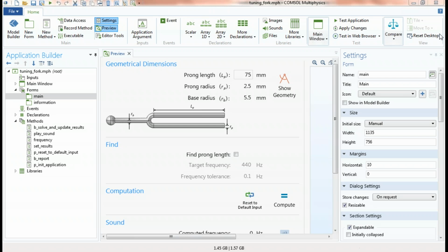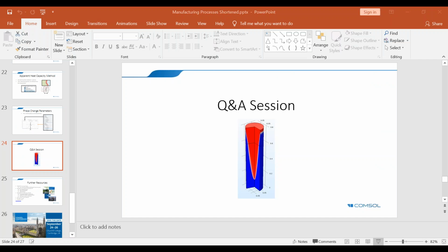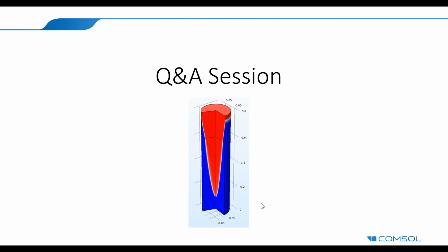So I think if you wanted to simulate this process, you would need to derive a force of some kind, which is acting on the fluid that's a function of the magnetic field. So it would be a volume force, I expect. Now, to my knowledge, I don't think that there is a predefined multiphysics coupling that you could use for that particular problem, but you could probably implement something yourself manually. So that would be added here within the fluid as a volume force like this, which would be derived from the magnetic field.